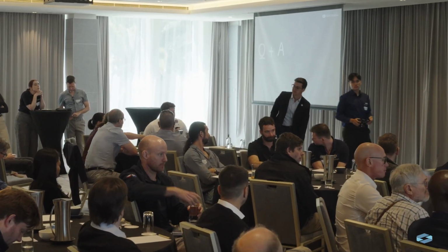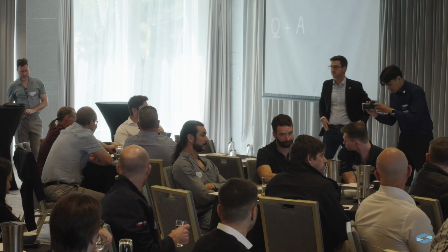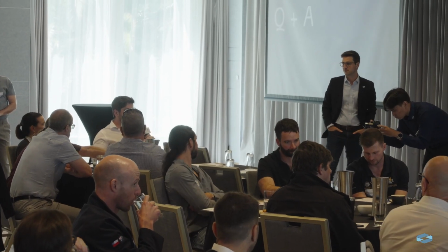Hey mate, Darcy here from Atlasine. The blast movement looked to be exclusively a blast by blast process. How do you manage where you've got blasted stock adjacent to the blast in question that's just gone off and you're about to design? How do you manage the impacts on that broken stock sitting up against the blast that's just gone off, on adjacent in situ? Because you would have a block out for the blasted stock that's sitting there. How would you manage the impacts? Is there a workflow that updates that block out as well?